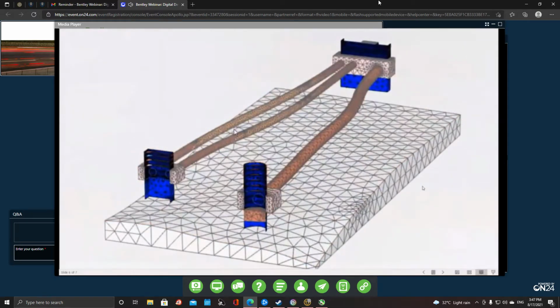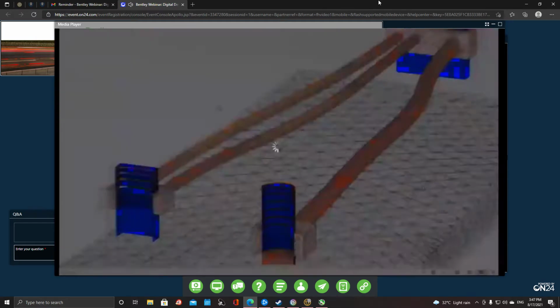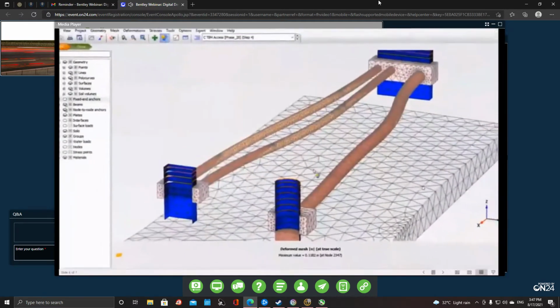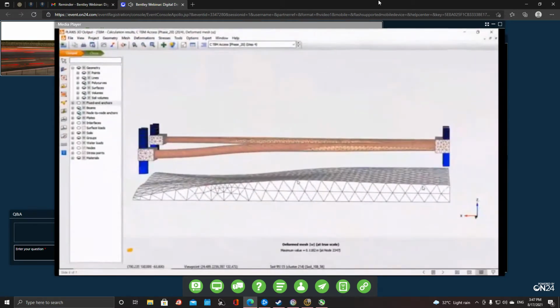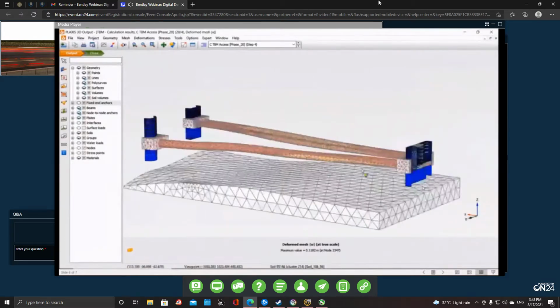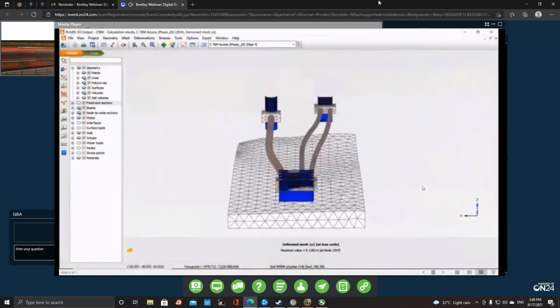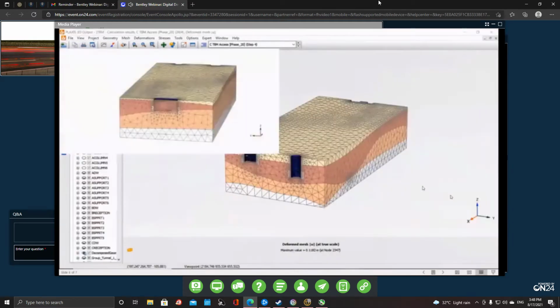Alignment of a tunnel is affected by a number of factors based on the end use of the tunnel and existing land use. For many urban tunnels, this factor controls both the vertical and horizontal alignment. On the contrary, there is often limited scope to alter the alignment in better ground though. Storage caverns are, however, a major exception, as economy of construction is often the governing factor.